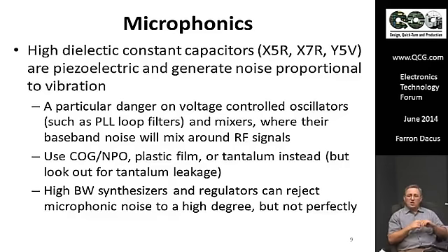In particular in frequency synthesizers, you tend to hang quite a bit of capacitance a lot of times on, say, voltage controlled oscillator power inputs, because there's noise on those supplies that will tend to degrade the VCO, and a natural tendency is to put a little RC filtering right on that VCO supply line. But if you're shaking the capacitor in the RC, if you've got a 1 microfarad X7R cap hanging there, you might find that generates tens of dBs of visible noise on that VCO.